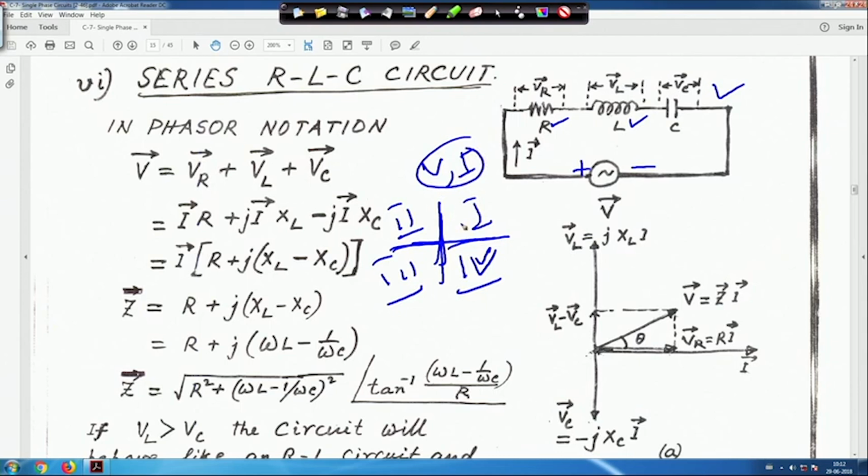According to your circuit diagram, network, angle, impedance, whatever type of circuit you have taken, the voltage or current phasor may be in the first, second, third or fourth quadrant. It may be in any of the four quadrants, anywhere, because it is a rotating vector. So that is the angle of the voltage and current.